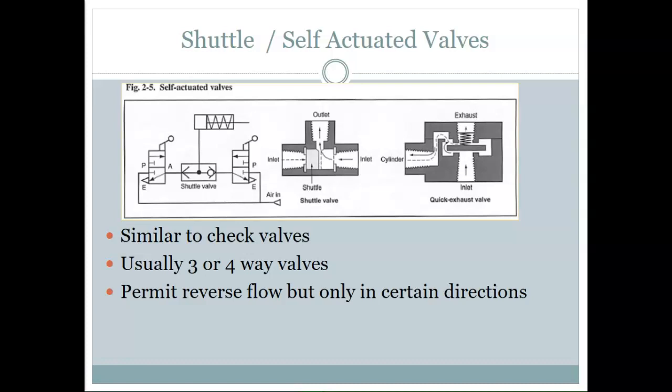The one we have here is the shuttle valve, or the one I told y'all was an OR valve. Now, why do we call it an OR valve? Well, it takes this or this to move this ball out of the way so you can extend your piston. It takes lever 1 or lever 2 to allow operation of the piston. So that's an OR valve.